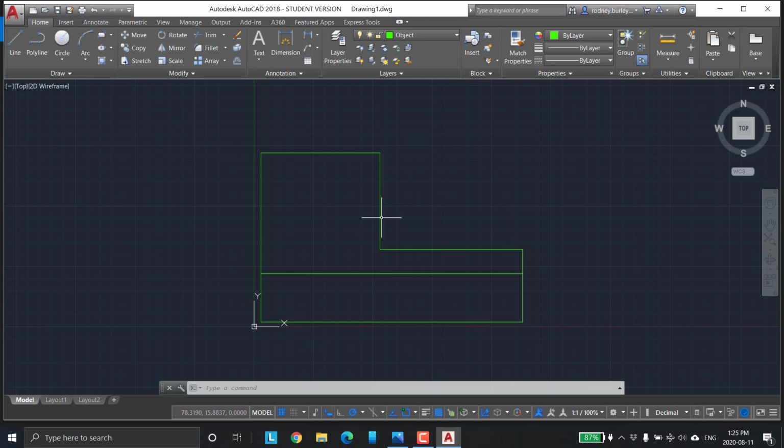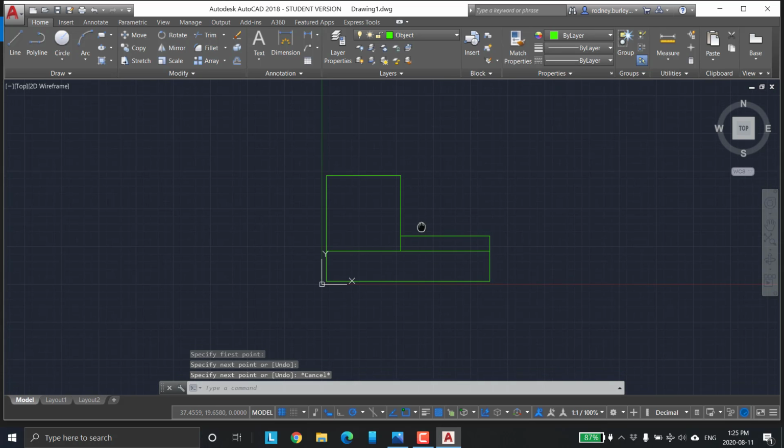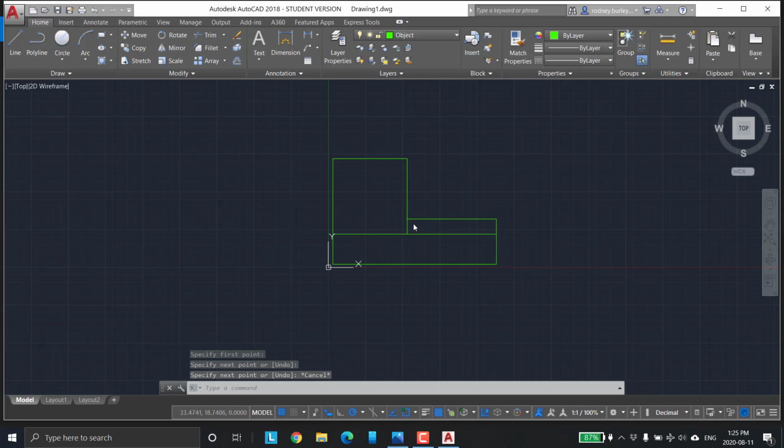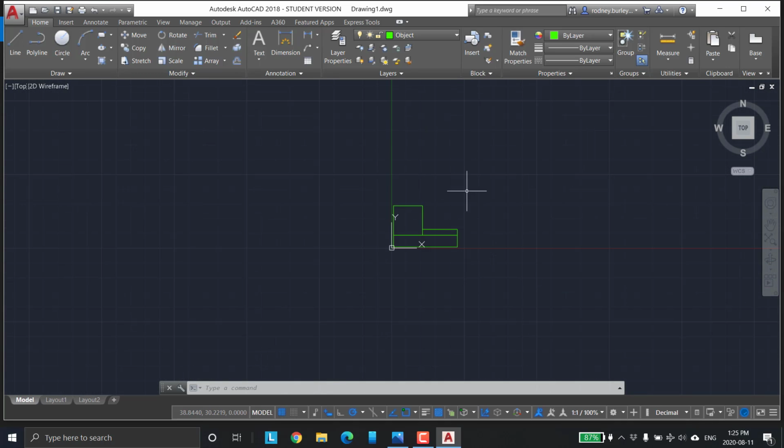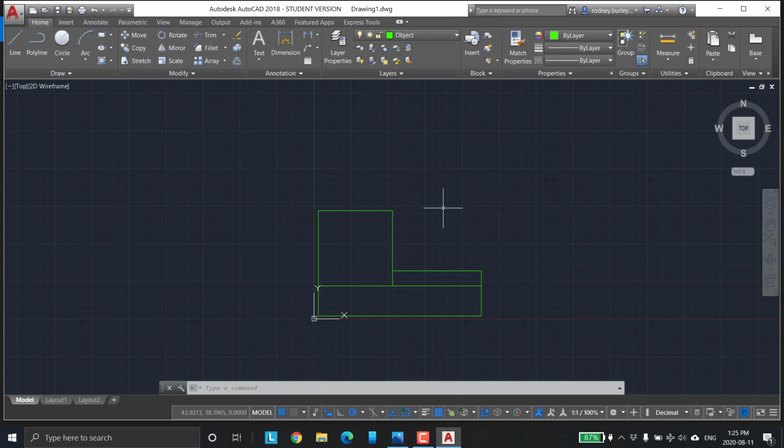So all you do is you could trim that down, or you can just go line tool, grab them here, go down to here, hit the escape key, and that's now done. Okay, so that's the view. So in the next video, I'm going to teach you how to draw the project up to the top, project over here, much like we did on the drawing board.